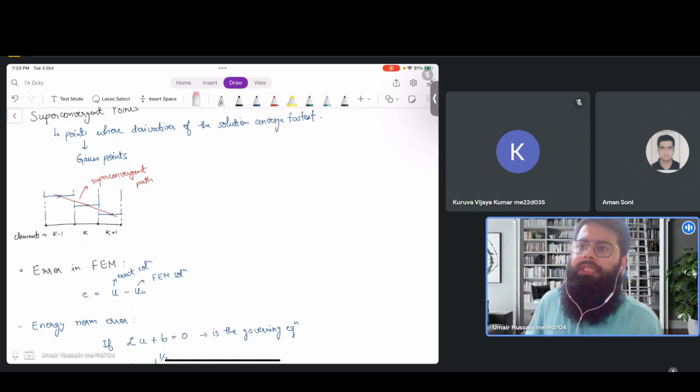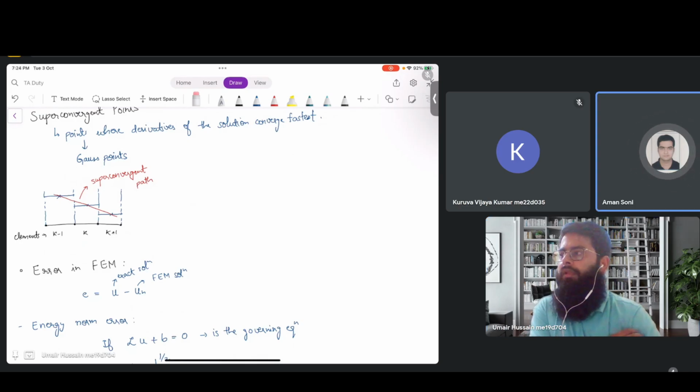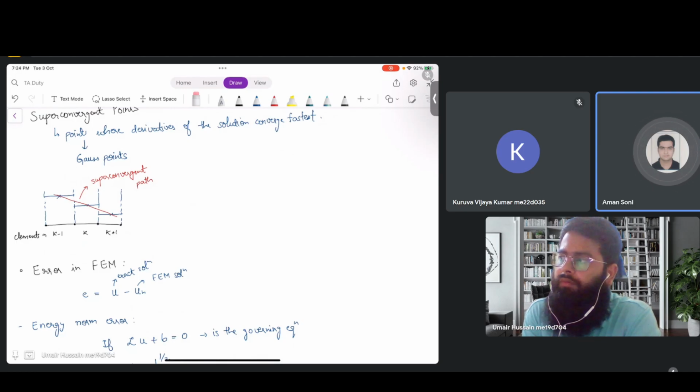In some cases, I think energy is also used as a parameter. Yeah, that is used in explicit solutions. LS-DYNA is one of the explicit solvers in which we use the error in energy. Basically, I think there is the first law of thermodynamics principle. Energy balancing is done by the software when we define any input file to the software. On the basis of that, it will calculate the error in energy.